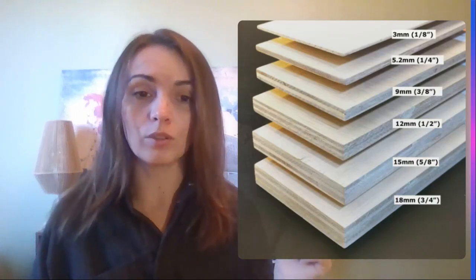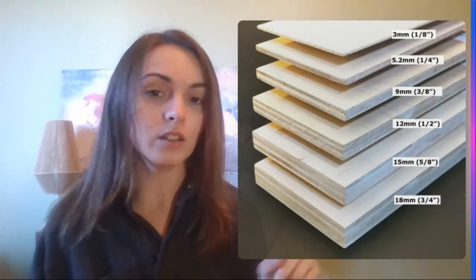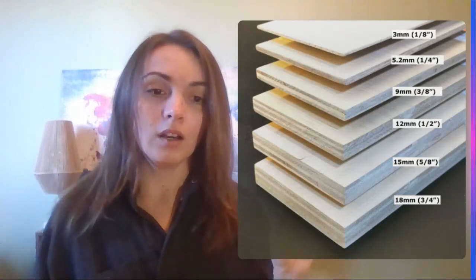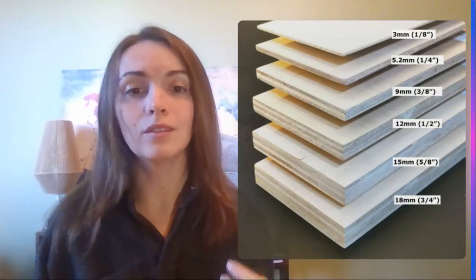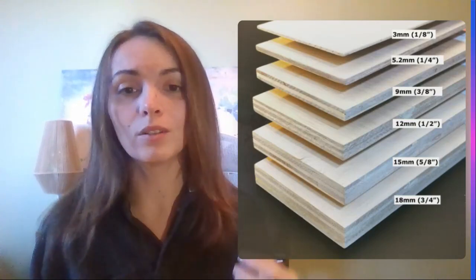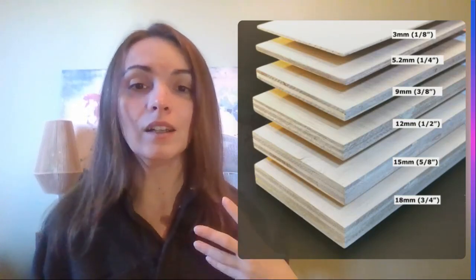And in this case, if we use only one machine, we always will get the biggest cylinder for the biggest board, even if only 1% of the time, or 10% of the pieces, will come for the wider board. For all other tasks, it means we will fill more compressed air, and we will get a hugely oversized system.